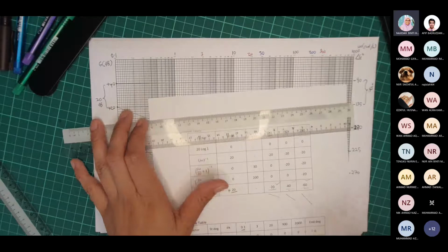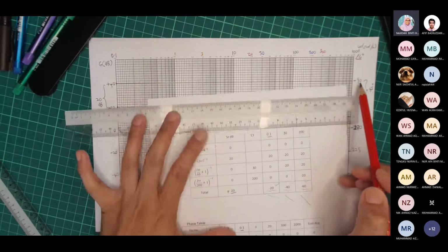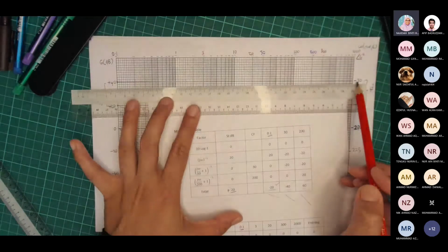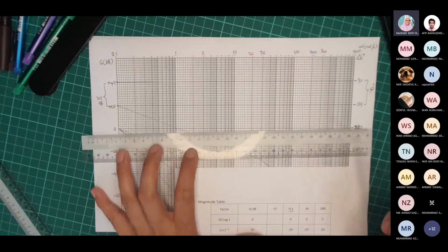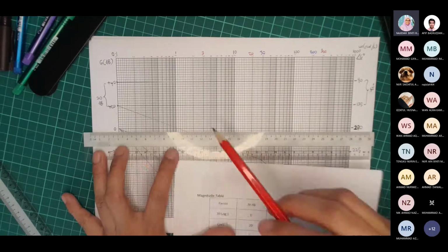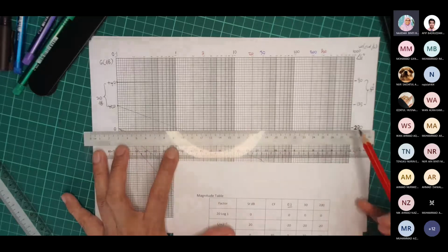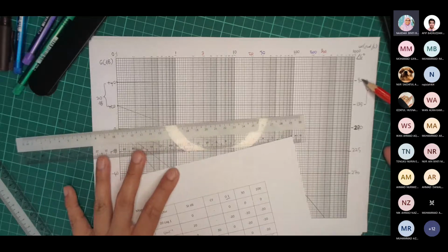For my phase plot, it starts at -90°. Okay, one famous question from the student: is it necessary to make sure that the 0 dB line is the same line as -180°? The answer is no. If you want, you can adjust the scaling of your phase plot a bit lower,